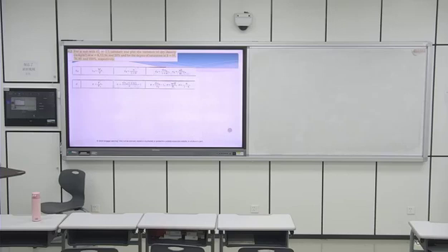Let's see one question in chapter 6. It says for a soil with Gs 2.7, calculate and plot the variation of dry density with water content of 8, 12, 16, and 20, and for the degree of saturation S equal to 45, 70, 85, and 100 respectively.